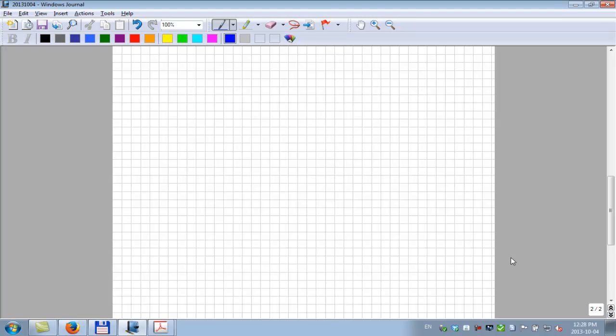So, all right, any questions? So we haven't really talked about how the procedure is done, but we'll go through that now. So we start the experiment. This is all at reservoir temperature. We start the experiment. The first pressure is equal to the saturation pressure. Could be a gas, could be an oil. So it's at the saturation pressure. In this volume here, we will just write saturated volume. It's a very important volume. And then we'll lower the pressure.